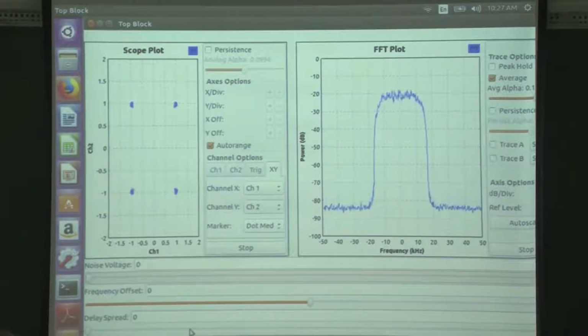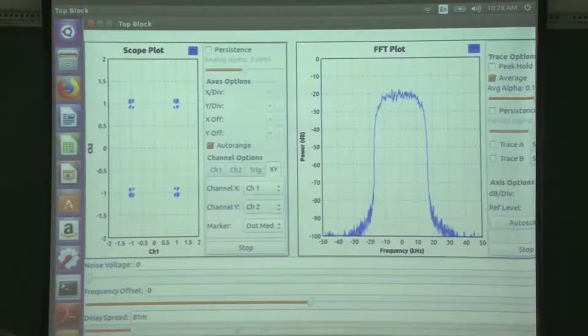Okay, let it settle. So now I am going to distort this portion. You should see what is happening in this system here. So let me just distort this. You can see that distortion here is creating multiple points on this side. These multiple points are called inter-symbol interference, because each symbol is interacting with the previous or the next symbol. So there are 4 points coming because this one is interacting with this and himself. So these 4 points come into the picture.